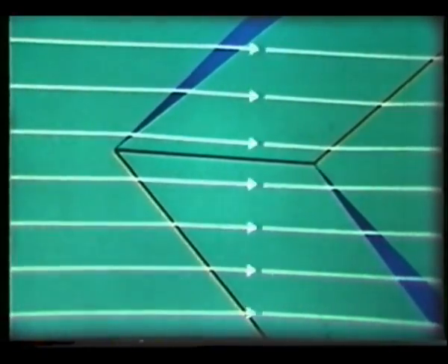Here's a wing section which would give lift at supersonic speeds, a thin, flat plate. Here is the flow pattern. On the upper surface, the pressure is less than atmospheric, as there's an expansion at the leading edge and a shock wave at the trailing edge. On the lower surface, the opposite happens, and the pressure is greater than atmospheric.